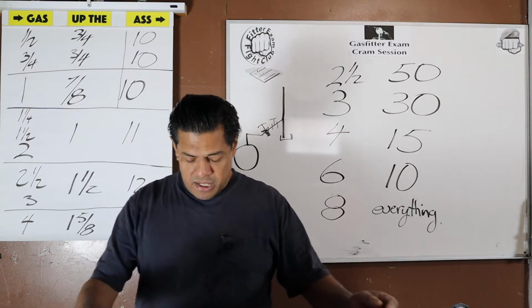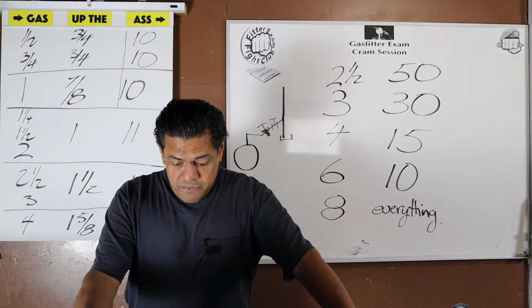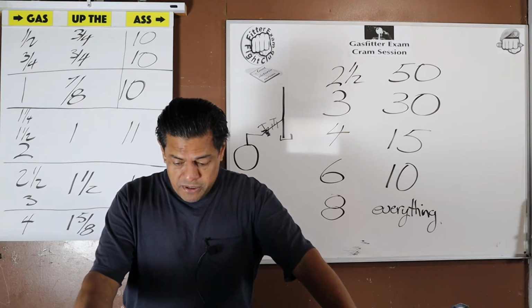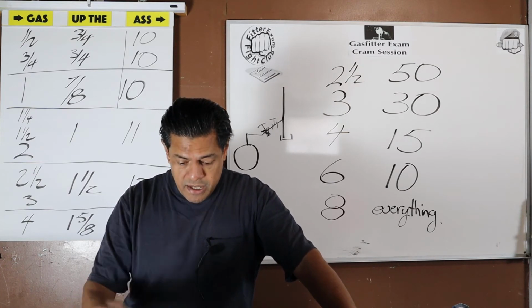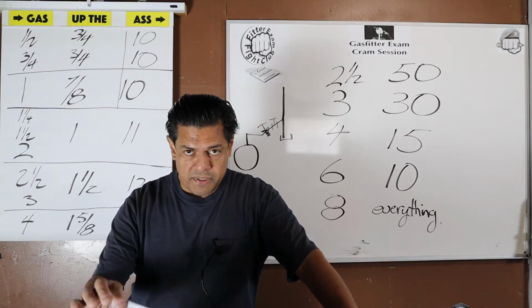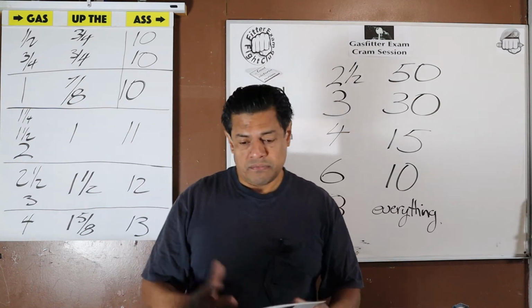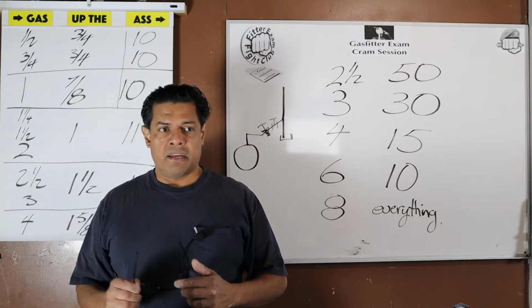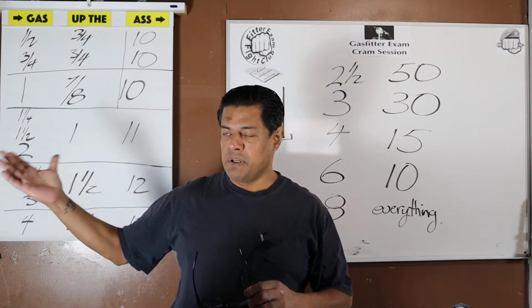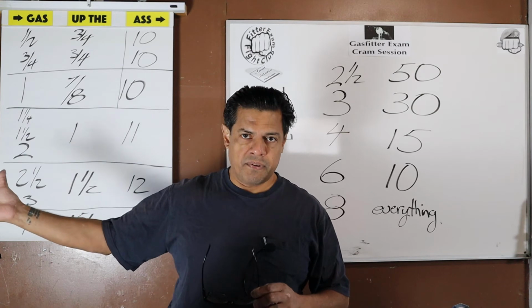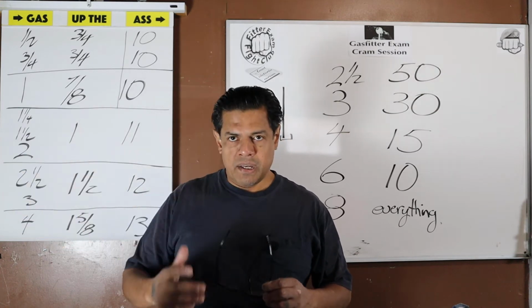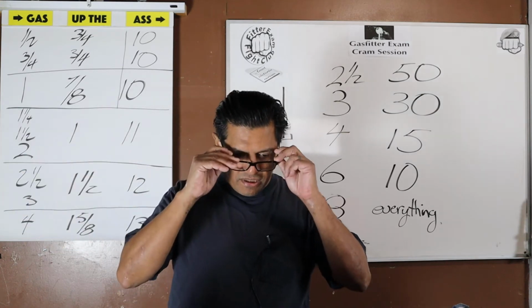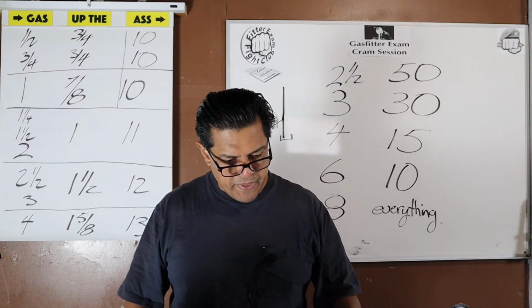But here, the volume of gas to be provided must be determined directly from the input rating of the appliance served. So, the appliance itself tells you what it needs. Figure out the total need of all the appliances, even if it's just one or all of them, and that's how much gas we need. The appliance tells you, input rating.